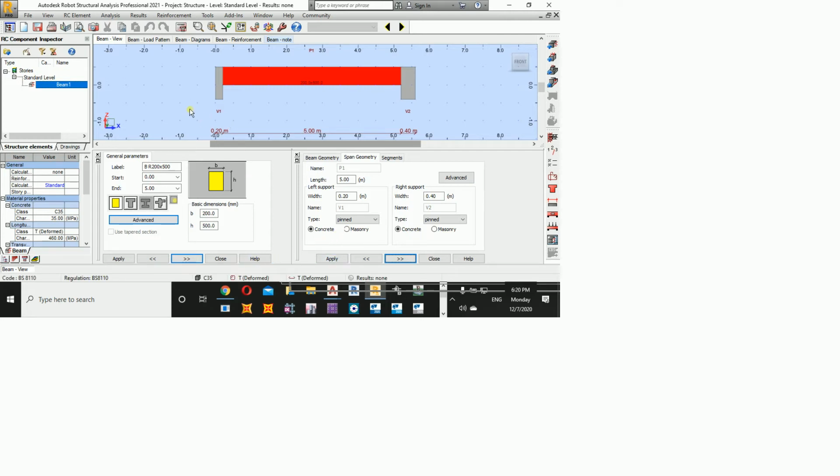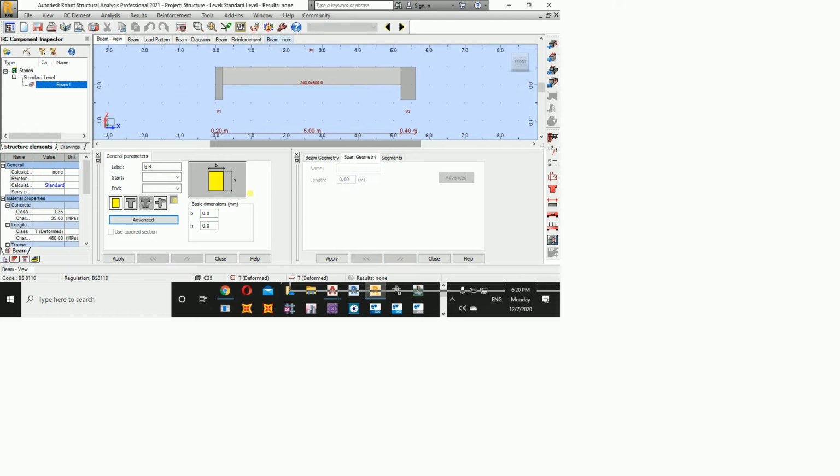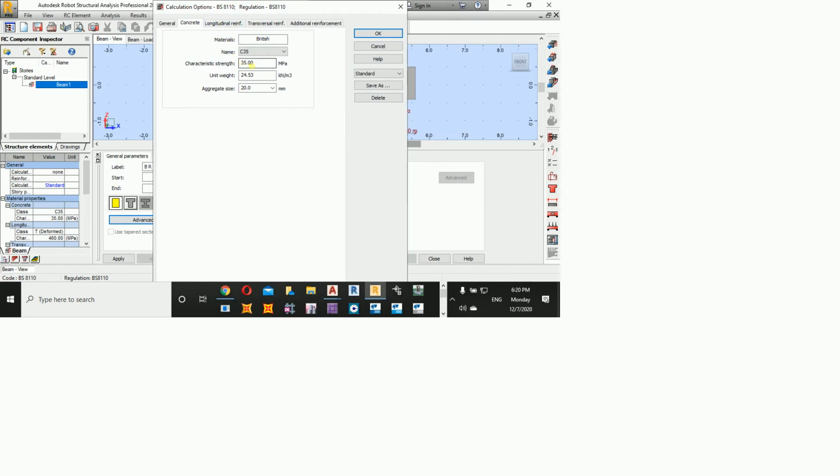Now when you click anywhere here, you will see that there are certain things at the bottom. You have a cube strength, C35. Not all of you are going to get the same ones, but we are going to modify. Can you double click wherever there is C35 for the cube? Can we keep it C35? If yours is C20, you should change it to 35.